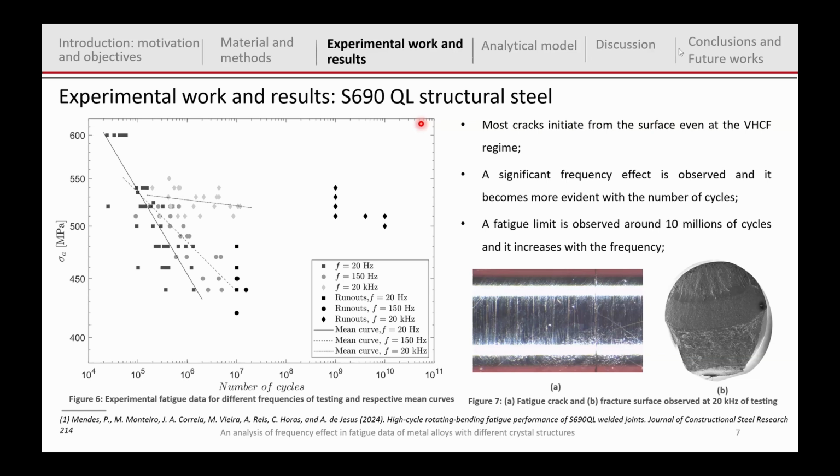We polished the specimens in the same way, and we controlled the manufacturing process. However, we have very different results. You can see here that the frequency effect increases with the number of cycles, and in fact is a non-linear behavior. So it will be more significant for a higher number of cycles. Besides that, we also observed the mechanism of initiation, and we observed that most of the cracks initiated from the surface, and we also have a frequency limit here around 10 millions of cycles.